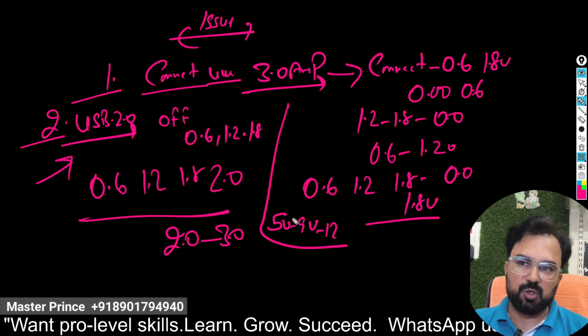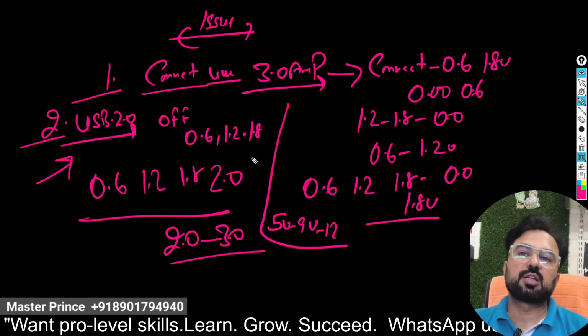When the phone switches to 9 volt or 12 volt, there must be an error on the secondary IC, or you can say the fast charging IC. Any line short circuit, the fast charging IC not working, or any communication fault, and when the charger switches from normal mode to fast charging mode after 2.0, it will reboot.